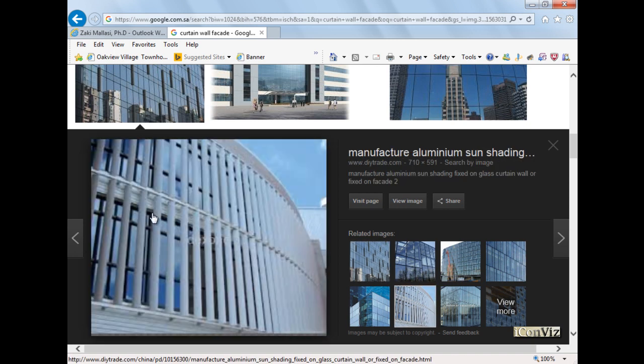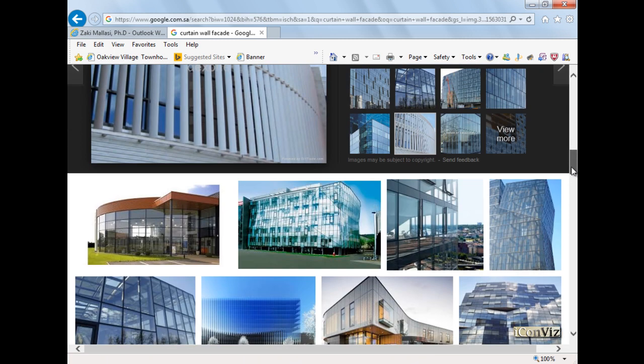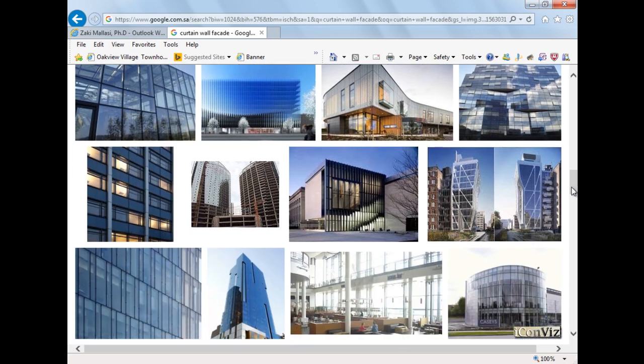This skin of this building is made up of 2 layers. The inside layer is a glass curtain wall, and then the outside layer is a curtain wall, but they switched off the curtain panels. So you use the curtain wall to create these louvers, vertical louvers. So there's many nice tricks you can do with the curtain wall. I want you to go ahead and now try it.